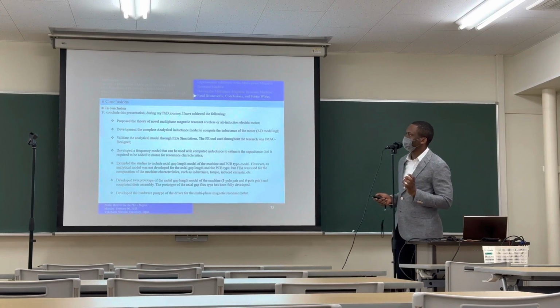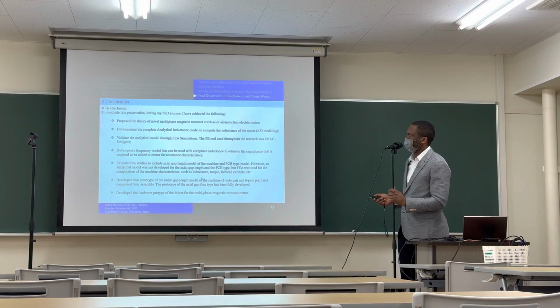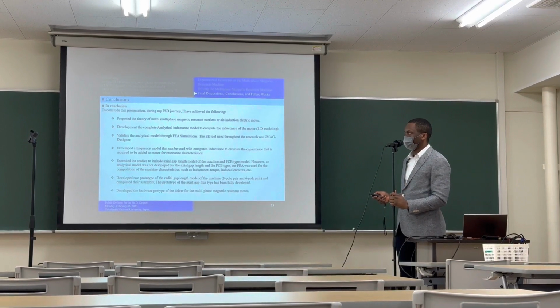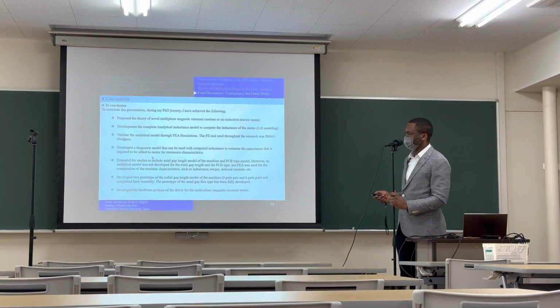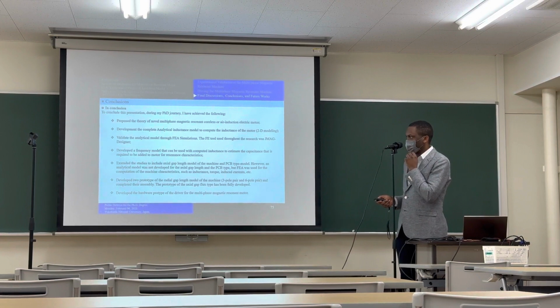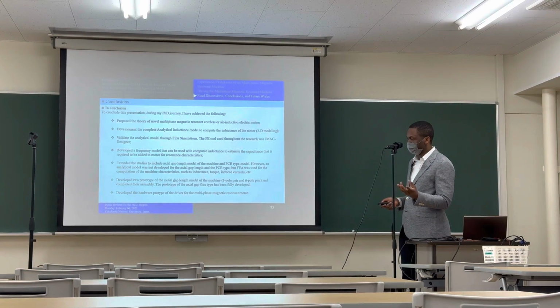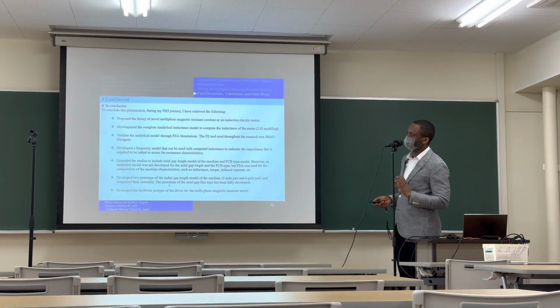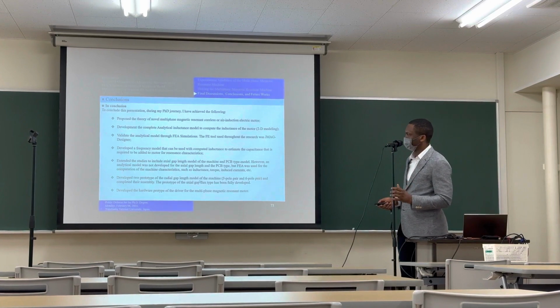So in conclusion, to conclude this presentation, during our PhD journey, I've achieved the following. We proposed the theory of this kind of machine, and then we developed an analytical model of the inductance. We corrected it many times, and then we used finite element analysis to validate the model that was developed. We also developed a frequency model, and used this frequency model to explain the capacitance that we need. We extended the study to include the axial gap type, and then further developed 3 prototypes, 2 radial gap type and 1 axial flux type. And then we have implemented the hardware prototype of the driver. So what is left is just to conclude and run more experiments.